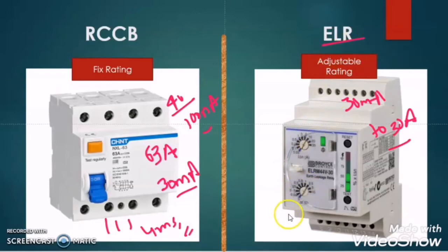For this example, if the dial is at 0 position, then as the fault occurs, this ELR will trip. But when we put the dial at 1 second, then it will hold the leakage fault current till 1 second and then it will trip the circuit. So this is the very big advantage of ELR over the RCCB.